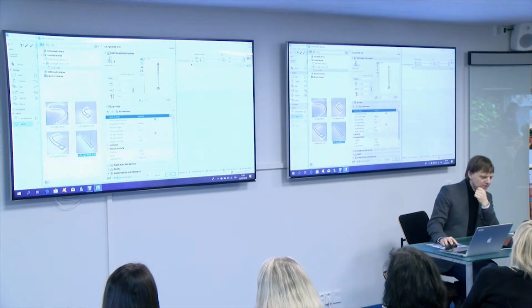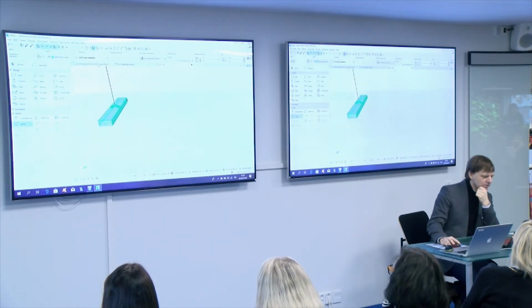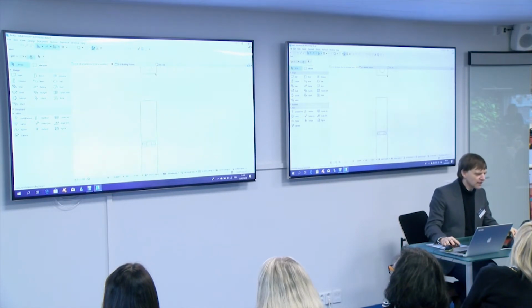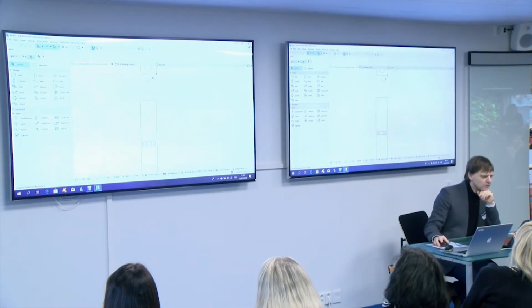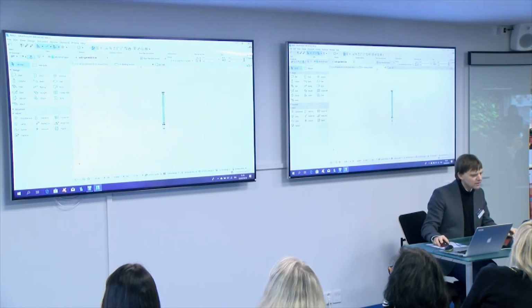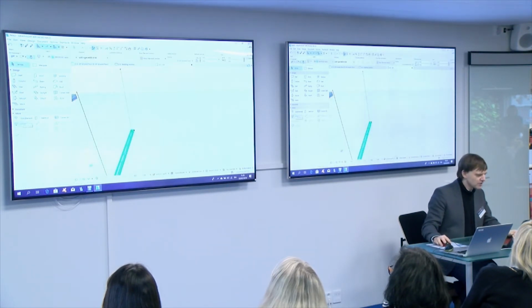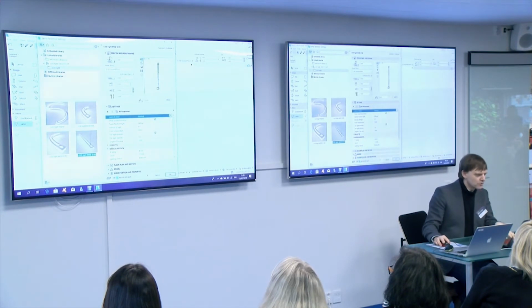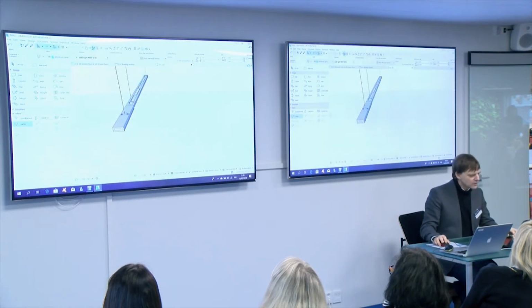And okay, let's put this in. Here we have to take care of the alignment manually. This is very convenient when there are just a few lights in the scene. Here we can see that we also have to adjust the height. We have to put it to 2,500, 2.5 meters, wire suspension 500. So now it is aligned.